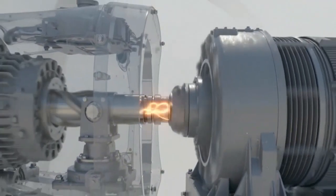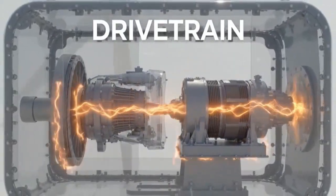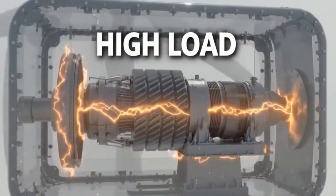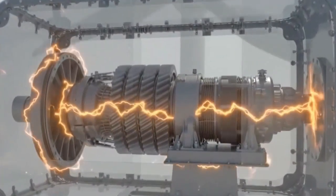From the low-speed shaft, rotation enters the gearbox, the component that changes the speed of rotation. Inside the gearbox, meshing gears convert slow, powerful rotation into faster rotation for the generator. The input side turns slowly with high torque, while the output side spins faster to match the generator.